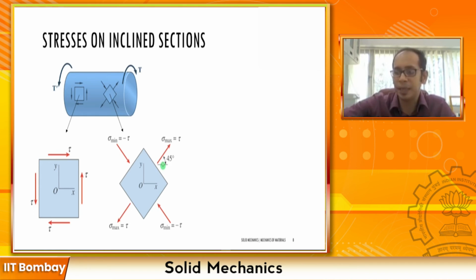And this is again very important when you are applying torque to members that are poor in tension and compression. Remember, this sigma over here is nothing but a tensile force, and this sigma over here is nothing but a compressive force, right? So even though your material may be good in shear, if the material is particularly weak in tension or in compression, classic examples being some brittle materials, in that case you are going to have a failure, right?